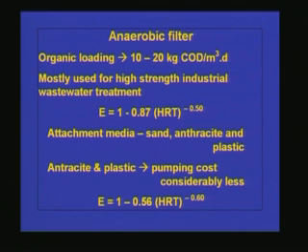Now we will see the efficiencies of each reactor in detail. As I have already explained, in the anaerobic filter we can go for very high organic loading, in the range of 10 to 20 kilograms COD per meter cube per day, and it is mostly used for high strength industrial wastewater treatment. We can derive the equation for efficiency using a kinetics approach, but there are empirical expressions available.